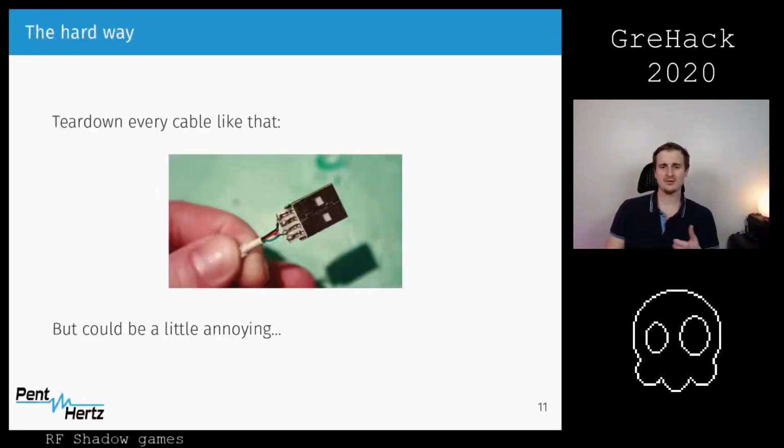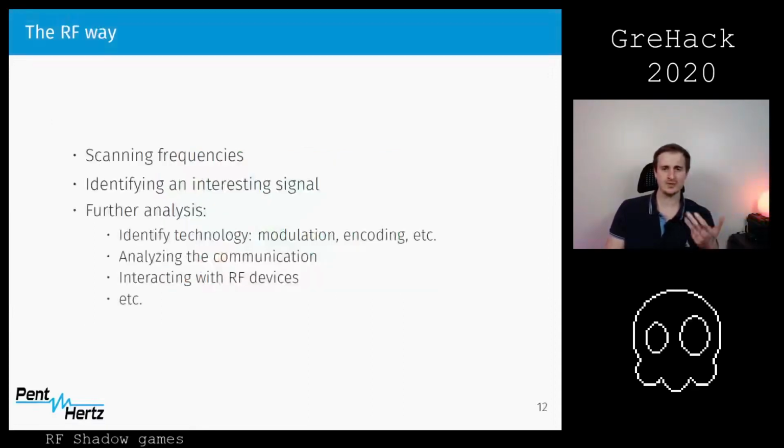So to identify the RF spy, there is the hard way. You can tear down the device or tear down the cable in order to be sure. This is maybe one of the most practical ways to do that, but you can also do it using RF, as I just showed, by scanning the frequency, identifying an interesting signal, then doing some further analysis on it.